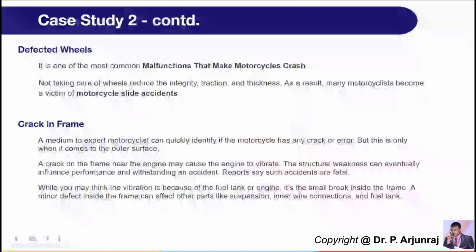performance. Okay, they can also do something. They can put dummies in a vehicle, two dummies, one for the rider and one for the pillion. They can run a bump test where the vehicle runs on a bump cam drum. They can run the vehicle at 15 or 20 kilometers per hour, and they can also induce vibrations artificially. Then they can see, because of that crack in the frame, whether any failure or any accident is going to happen.